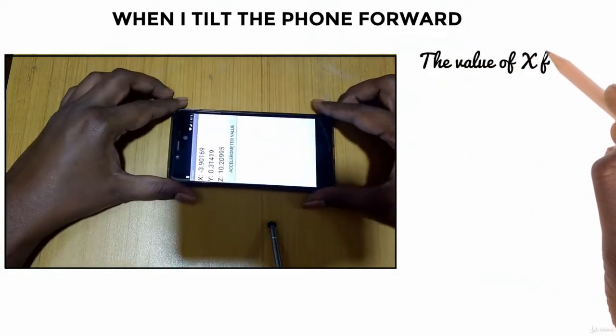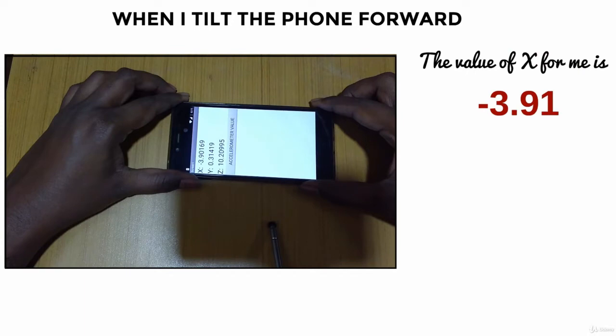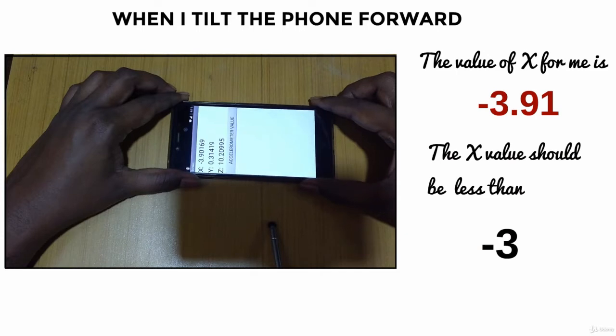If I tilt my phone in the forward direction, and now if I click on the button, then you can see I'm getting the X value to minus 3.91. So minus 3.91 is less than minus 3. So if I want to move the robot forward, then the X acceleration value should be less than minus 3. That is minus 4, minus 5.